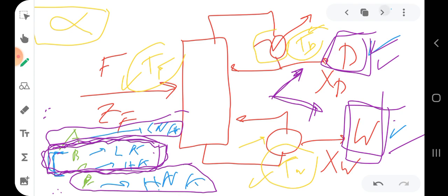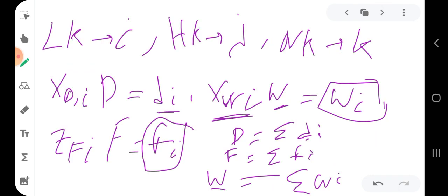How are we going to get this average? It is the relative volatility of any component I, with respect to the heavy component as we mentioned before. If it is not averaged, you need to average it, based on the relative volatility in the distillate, in the waste, and in the feed at different temperatures.